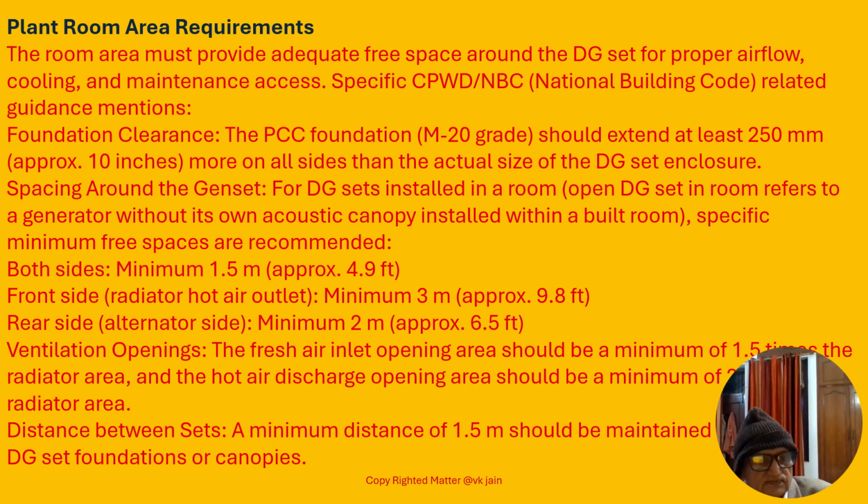Ventilation opening, the fresh air inlet venting area should be minimum of 1.5 times the radiator area, and the hot air discharge opening area should be a minimum of 3 times. Distance between two sets: if you are mounting two different sets, then a minimum distance of 1.5 meters should be maintained.